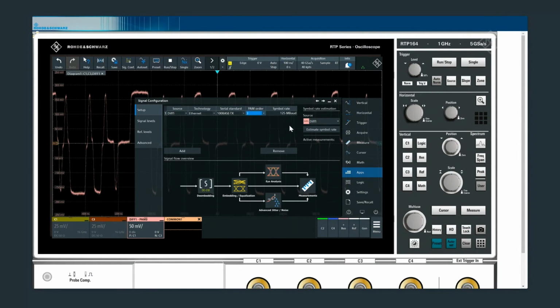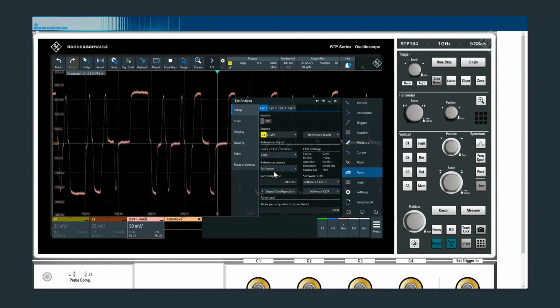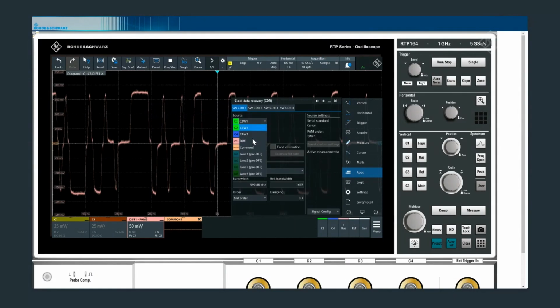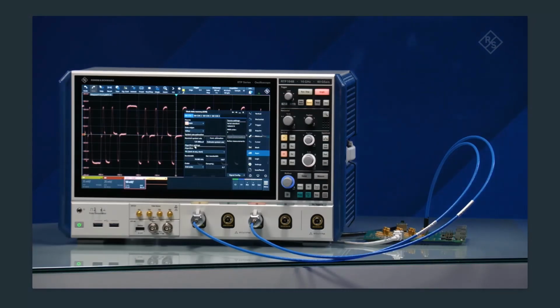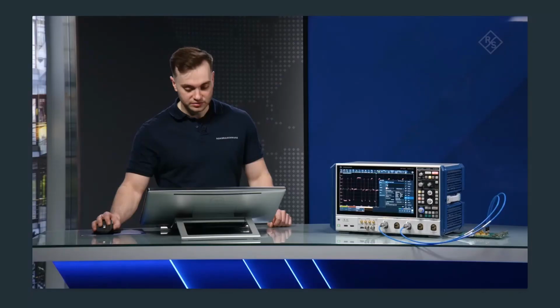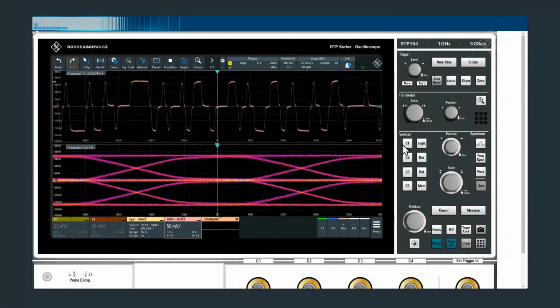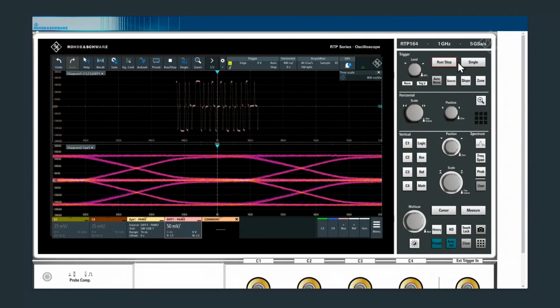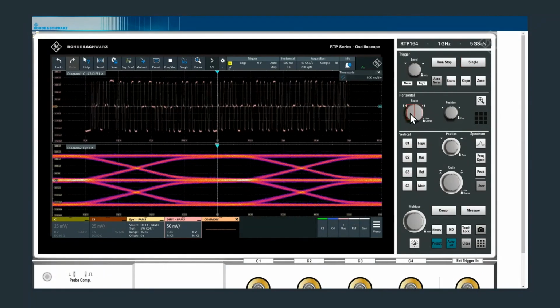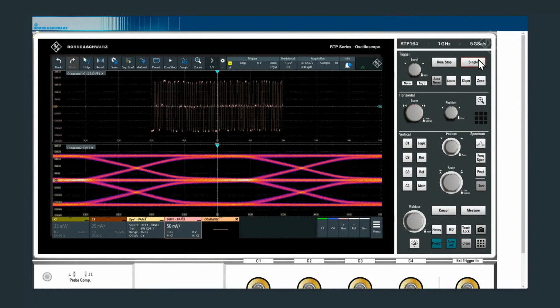megabit per second. So again, we have the same signal flow overview. You know, we could do some de-embedding, we could do some embedding and equalization, but let's jump straight to the eye analysis. We'll change our source to differential 1. The CDR will already be checked and changed to 125 megabaud. And we can then enable our software eye here. We have a few edges. You can see that we can give it a bit more data. And we start to fill in this PAM order level 3.